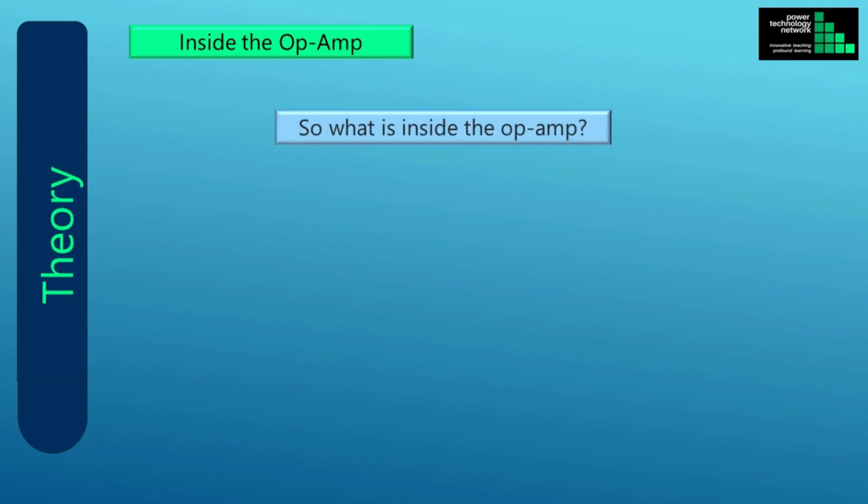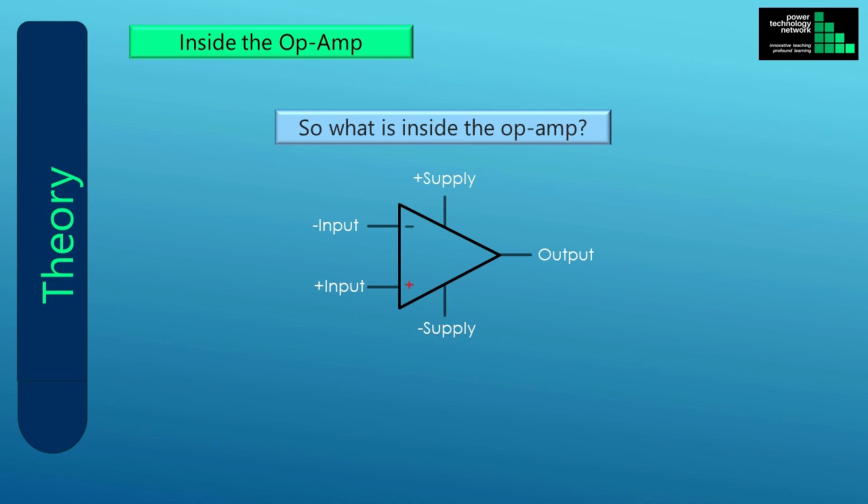We have already presented the op-amp as a three-port device. There is the differential input, consisting of two input terminals. And the two input terminals are designated as the positive and negative input terminals of the op-amp. Then, there is a single-ended output terminal, where the amplified version of the voltage difference between the two input terminals is produced. Finally, there are the two power supply connections where the power comes from to produce an amplified version of the input signals.